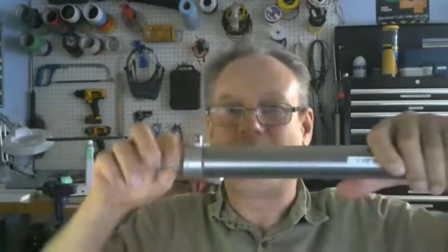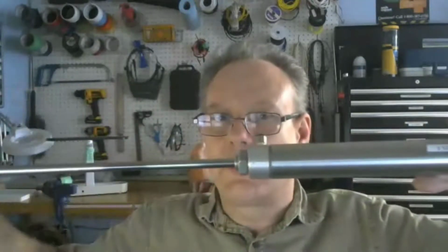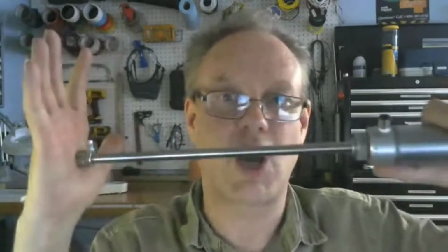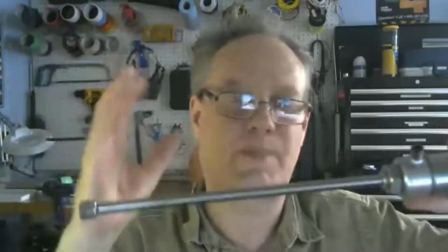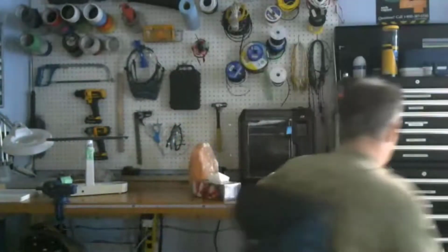But during extension, there's a lag in pressure because there's a flow rate filling this great chasm. And if that chasm's bigger, the lag in pressure is even more. But ultimately, the application force happens when it stops. When it stops, that pressure goes right up to system pressure. So, great example. I really love that discussion.